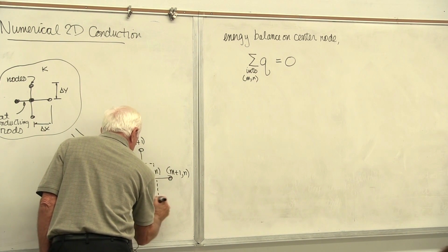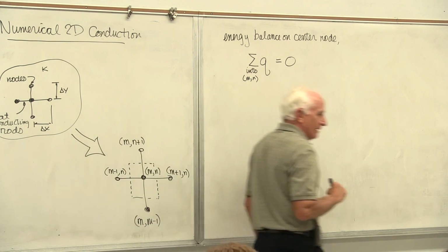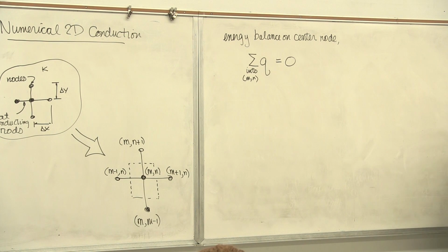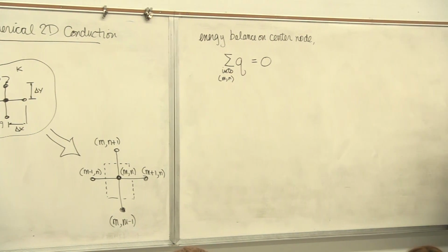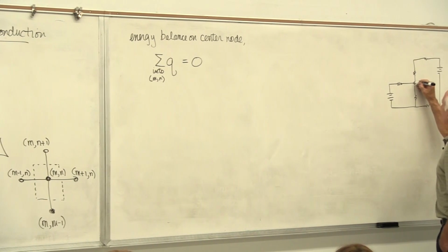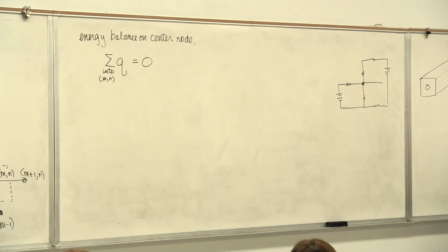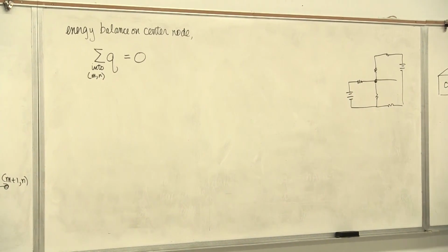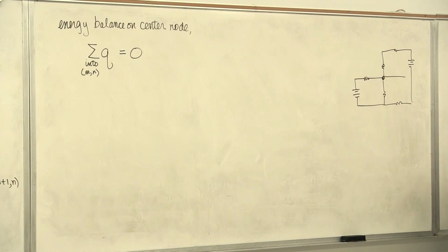A lot of times in electrical engineering, we'll have some circuit, and if you don't know the current in this circuit, whatever it might be, I'll make up something fictitious here. And at this node right here, sometimes to solve for the unknown currents in DC circuit theory, you'll say, I'm going to write the nodal equation. The sum of all the currents into that node is 0.